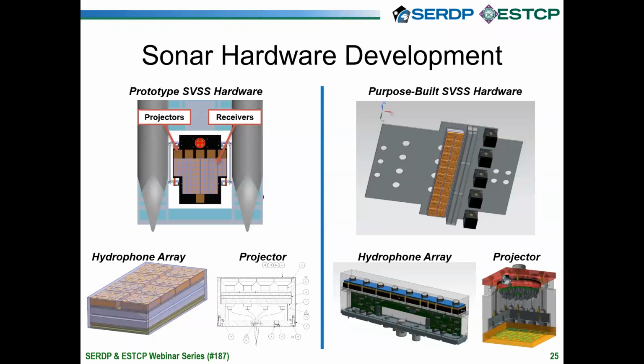In fact, we're able to extend beyond a 16-bit dynamic range. So we're going to be digitizing this data with 24-bit receiver cards, and we anticipate that we will have in excess of 18 bits of dynamic range available from this. So we're going to be able to receive signals that are much weaker than we had been able to with